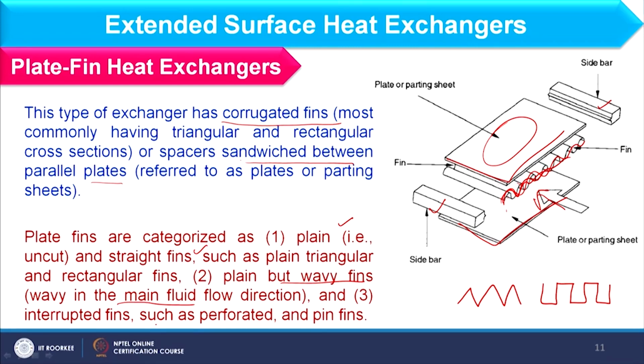Okay, and interrupted fins with some perforation and pin fins, okay. Because of this perforation or pin fins, we can have more turbulence, so we can increase the heat transfer coefficient. Now the point is where I am using these fins. Where I am finding a lesser heat transfer coefficient on an extended surface, there we consider plate fins, because we are increasing the heat transfer area in that particular section.